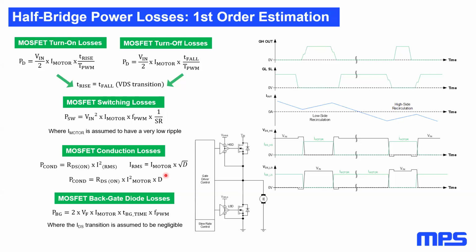Or you can make a very simple assumption that you have the trapezoidal current that flows in the high side minus the DC current component, because the current that flows in a capacitor in a PWM cycle has to have a net zero for the system to be in equilibrium. So you can assume that current minus the DC bias is your waveform, and calculate the RMS of that.